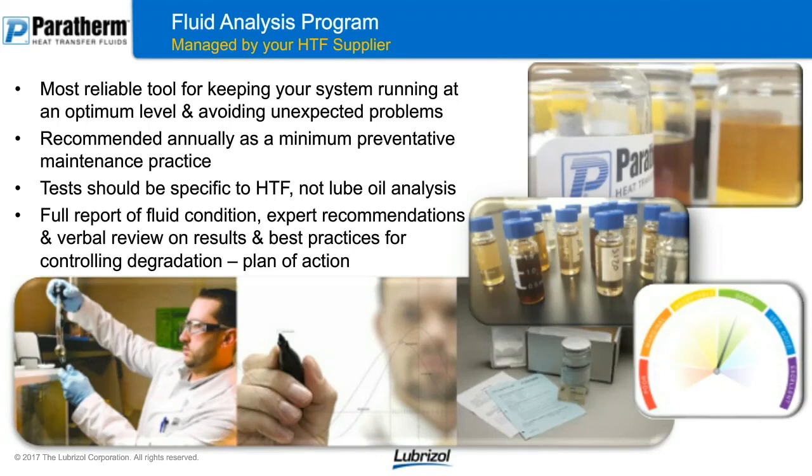What you need to do is make sure that if you have any problems, you're seeing decreased temperature outputs or you're getting cold spots in your system, the first thing you should do is have a sample tested by a professional heat transfer fluid analysis lab. Key point, don't do it with a lube oil analysis. The tests are different. They should be specific to a heat transfer fluid.